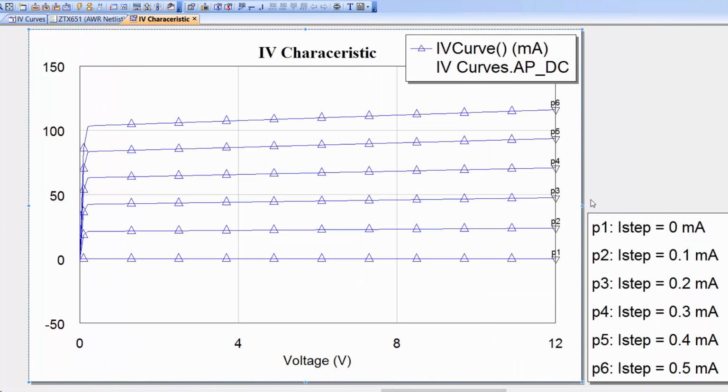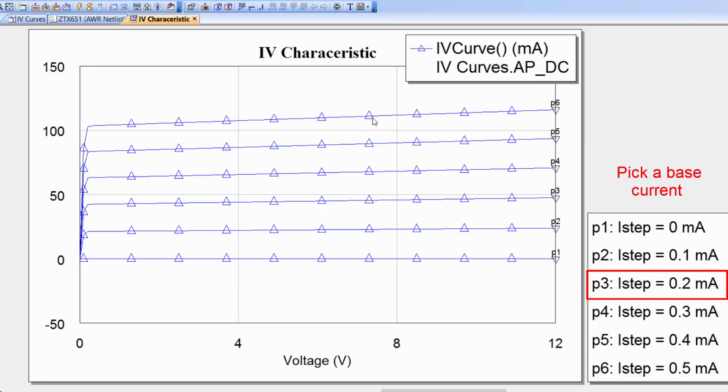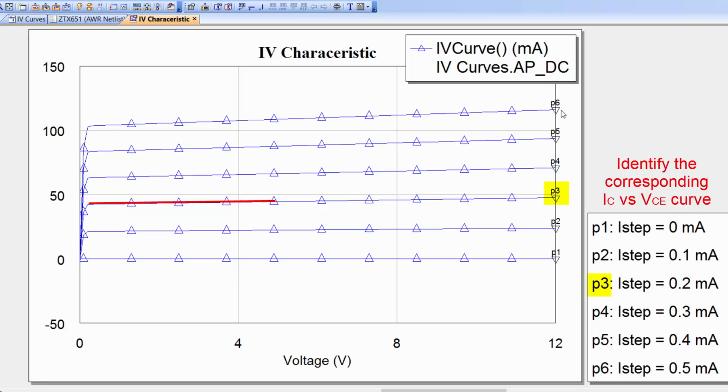You can see that the IV curves look exactly as they should, and also that this transistor looks relatively realistic because, for example, we have the Early effect, which is represented by this model. So this is quite a good model that is also giving us the effects that normally in an ideal transistor you shouldn't see. These lines should be perfectly flat, whereas they have some degree of slope, which is due to the Early effect.